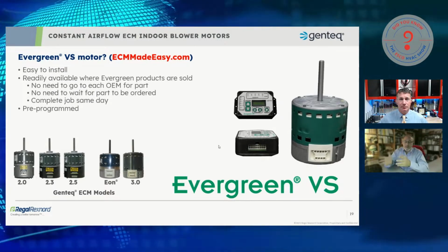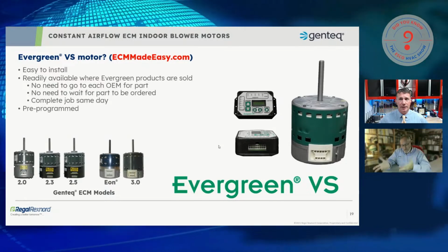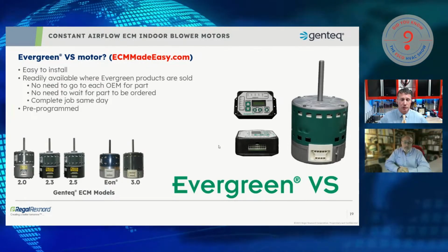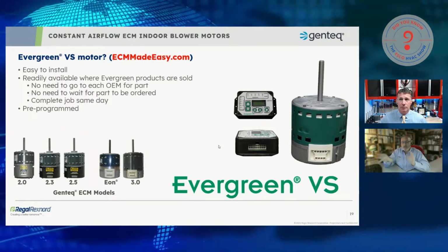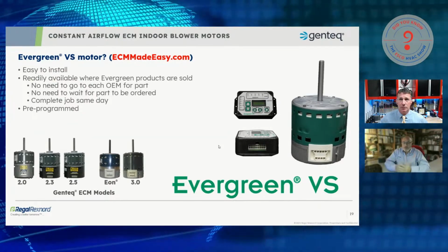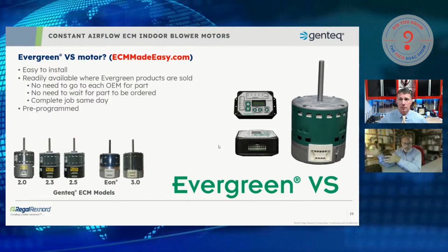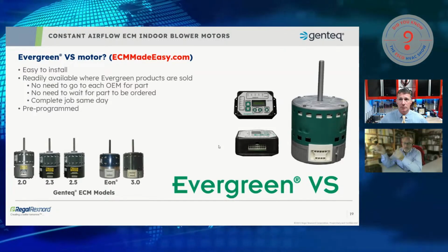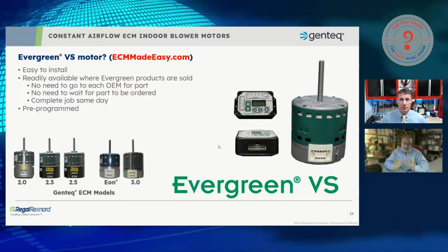We can't possibly know how 20 million motors were programmed, so we don't even try. We simply move all the airflow adjustments to this box, so you can manually control it. You can set the airflow on this box. So the technician that's always done things the right way, has always set the dip switches, is going to throw that argument: well, now I have to set the airflow here. I know I set it up perfectly on this system because I installed it 10 years ago, and now I have to do this again. Well, yes, that is true.